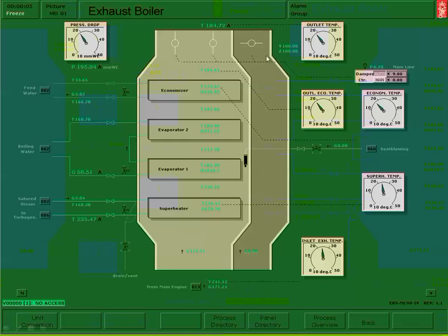These dampers, the Europeans were using this to regulate steam pressure instead of the dump that I just said. Makes almost no sense to me. What would happen is, like right now, this bypass is closed, so all the gas would be going up through these tubes and generating steam. Well, I've got a steam turbine. I'm combined cycle. Why would I ever want to bypass that?